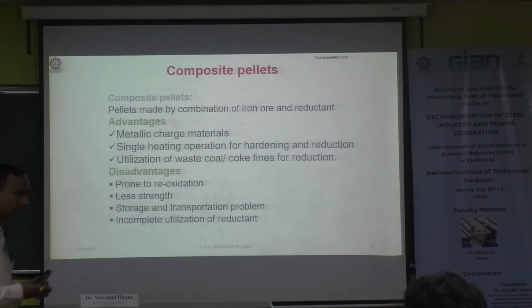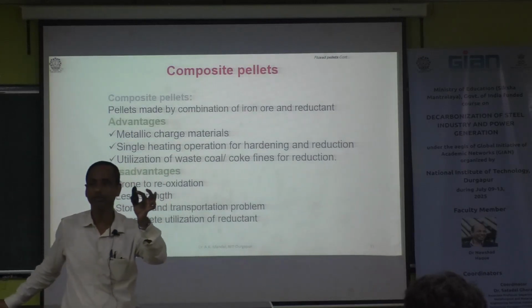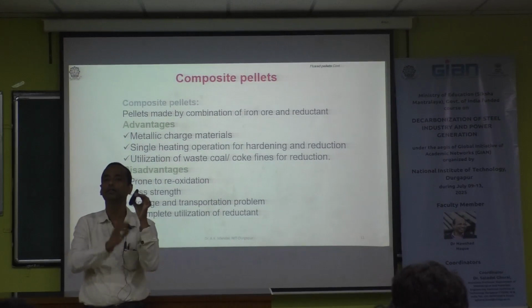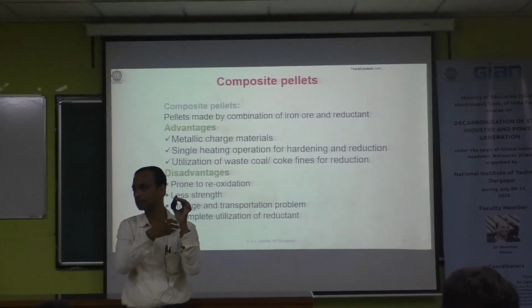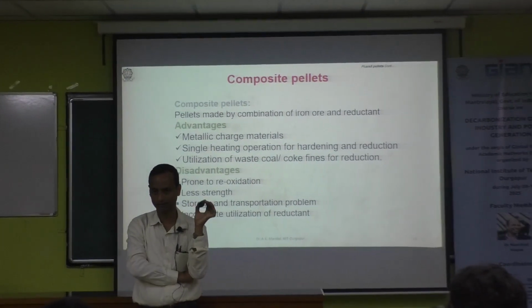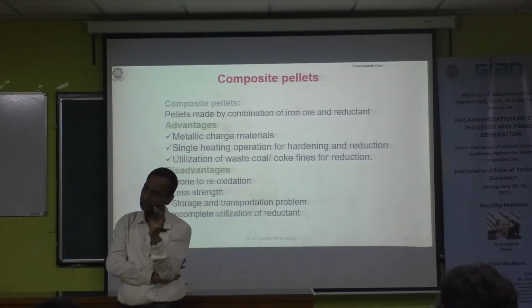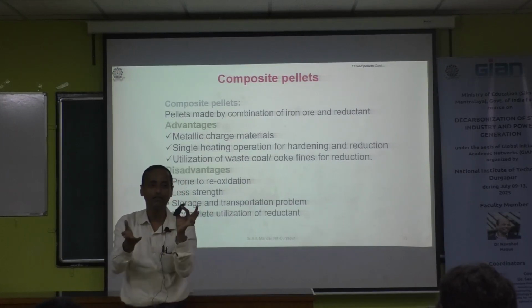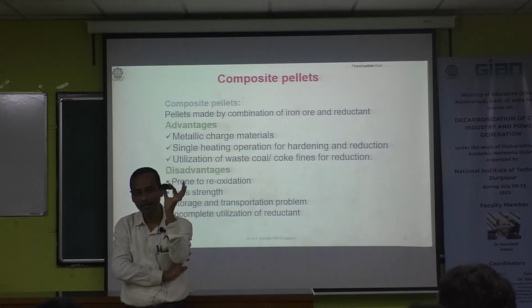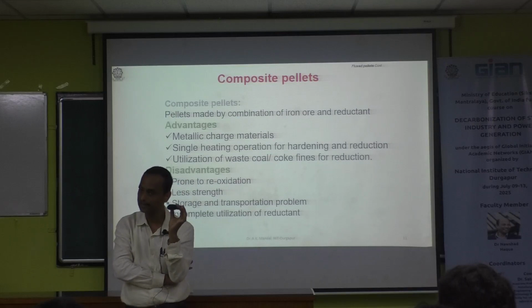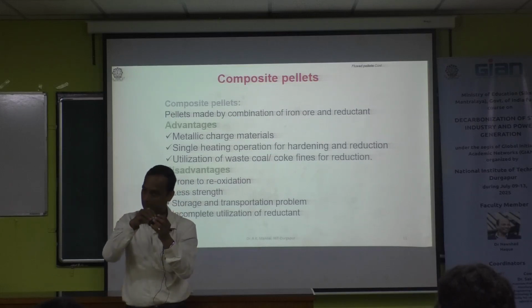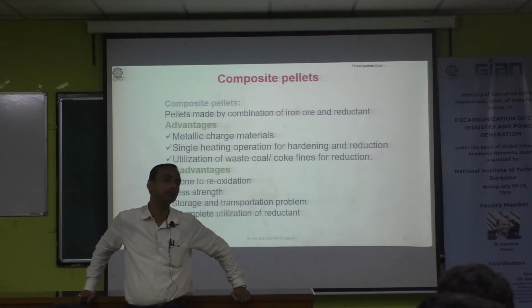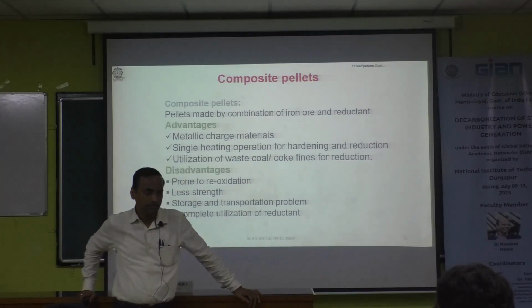It means, suppose this is your pellet. It contains 10 gram Fe2O3. If you calculate, to reduce 100% of 10 gram Fe2O3, suppose X gram of carbon is required. So is it possible to reduce 100%? And 100% reduction is obviously not possible. If you put X gram reductant, will it reduce 100%? Why will it not reduce 100%?